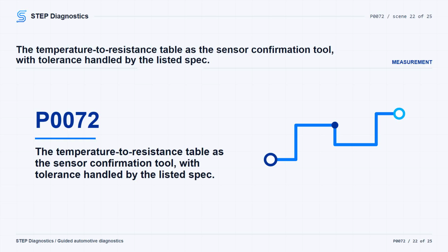Key checkpoints are: -40°C/-40°F/345.26 k ohms, lowest possible temperature reading; -10°C/14°F/53.38 k ohms, logical temperature values; -5°C/23°F/40.89 k ohms; 0°C/32°F/31.56 k ohms; 5°C/41°F/24.55 k ohms; 10°C/50°F/19.24 k ohms; 15°C/59°F/15.22 k ohms; 20°C/68°F/12.13 k ohms;